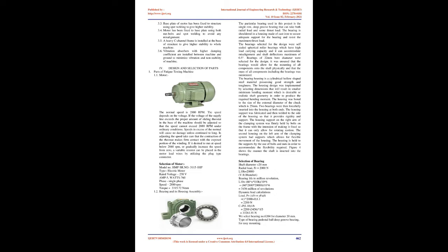Structural issues. The supporting structure consisting of hollow square bar was not capable of carrying the static and dynamic load of the upper components. Due to absence of any damping material between structure and ground, the whole machine became highly unstable while running. Modification required. To minimize all these faults, we designed and modified the whole machine using the following modifications.